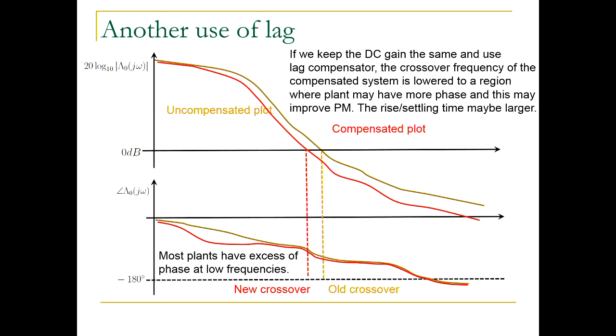All right, so in this lecture, we would actually use this method to increase phase margin using a lag compensator. So, you know, it's sort of counterintuitive from the word lag and from just the phase plot for the lag compensator. It's going to subtract phase. No matter what you do, it would always subtract phase. But since it can also move the crossover frequency, you can actually increase the phase margin. It's sort of counterintuitive.